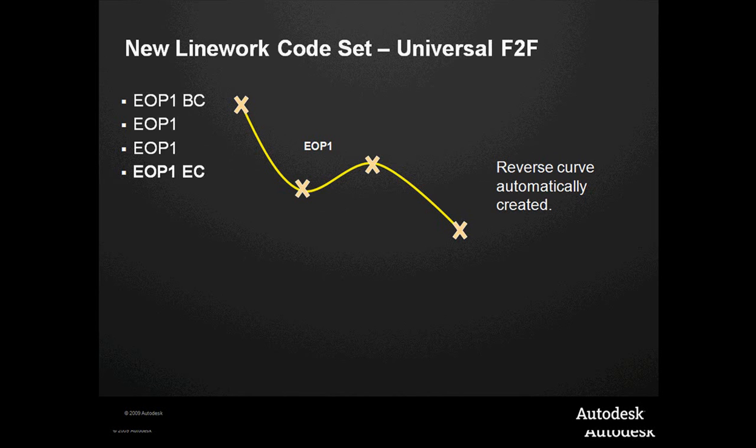Okay? At the same time, if I'm worried about taking shots and I want to get a true horizontal distance between lines, and now these things are sitting in space how they were actually shot, within Civil 3D we can apply a style to the line work to say, we know it's got 3-dimensional qualities, but I want to display it only as a 2D object. So now as we take measurements, curves are all horizontal distances. So it's a matter of what style we apply to it is what we'll get. Okay? Yes, sir.